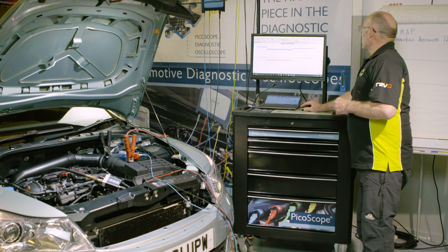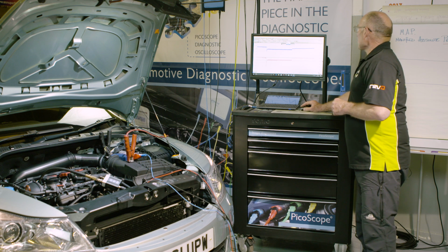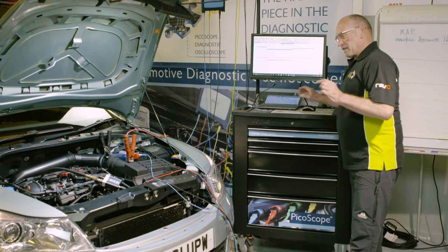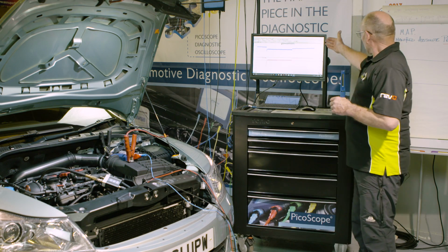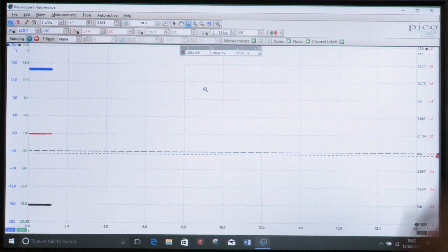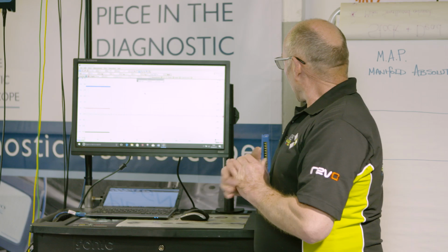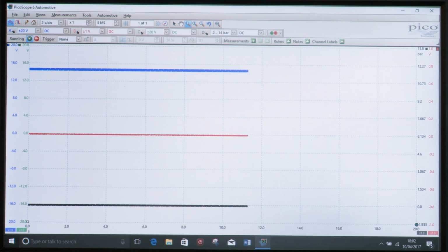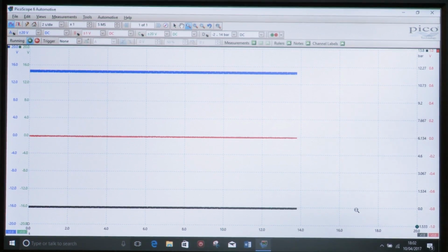And I'm going to suggest that the 2 to 14 bar is more than enough, because one of the interesting things you'll notice, so we have now got a measurement range actually in pressure, and you'll notice that we have some very interesting results, because potentially the pressure in this engine will be, say, 10 bar, thereabouts. What you're going to see in actual fact, when the engine runs, the pressure is actually much less than that.